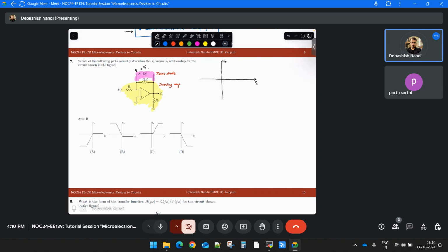In the forward direction, it is just a forward-biased diode. In the reverse direction, it will just flow current and it will suddenly drop. This value we call VZ, the Zener voltage, right? Yes, sir.